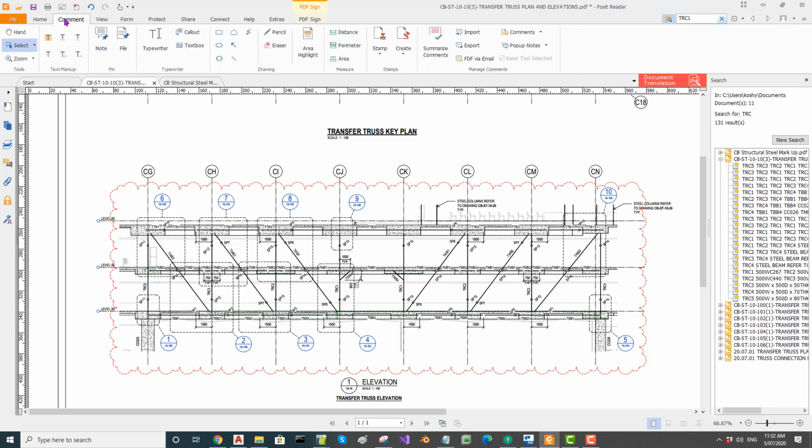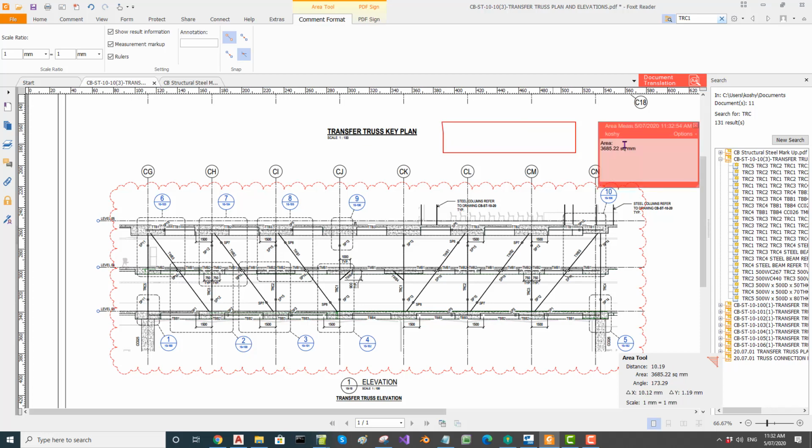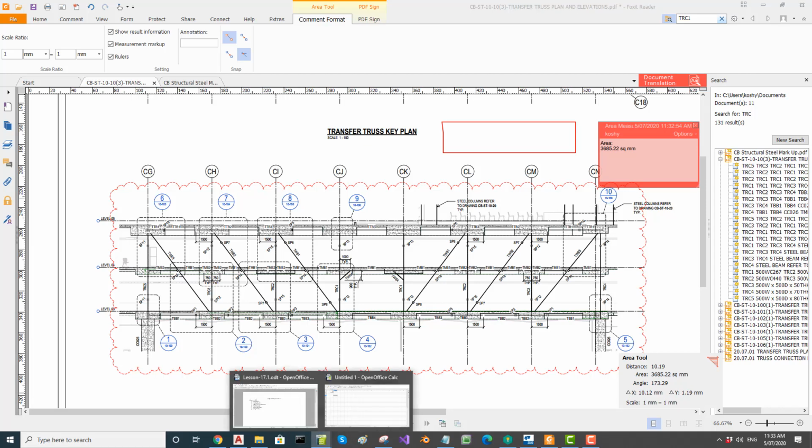You can also measure area by creating an area. Where is that? By creating an area by picking points. So I select here, here. Keep the shift key pressed if you want to go horizontal or vertical. Right click, complete measurement, and it gives me an area here. Again, you can see the scale here. You have to watch the scale. You might have to adjust the scale, use Excel and calculate.